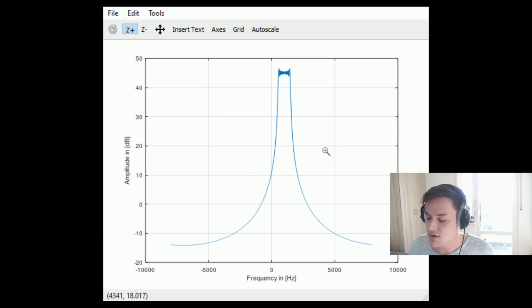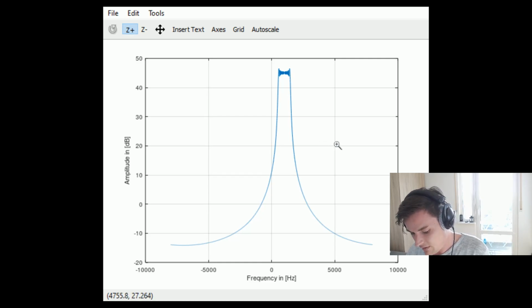Also in the field of radar you use chirps, because the cool feature about a chirp is that it spreads its energy over time. So you don't need high peak powers, which maybe would break your amplifiers. Instead you can use a chirp signal and spread the energy over time. But that's only a very high level note.